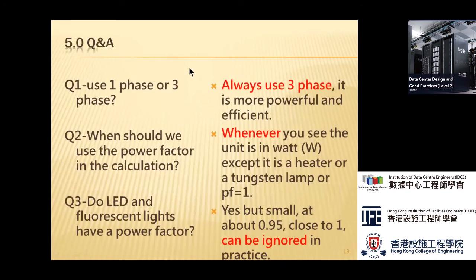Now let's move on to the next one, which is about the Q&A. Let's talk about Q&A. Now suppose Q1, right? Use single phase or 3 phase, which is better? Well, if the power is larger than 3 kilowatt, as we mentioned before, if the device is more than 3 kilowatt, it's better to use 3 phase because it's more powerful, more efficient, less cable size, less money maybe. Although you use 3 different cables instead of 1 cable now.